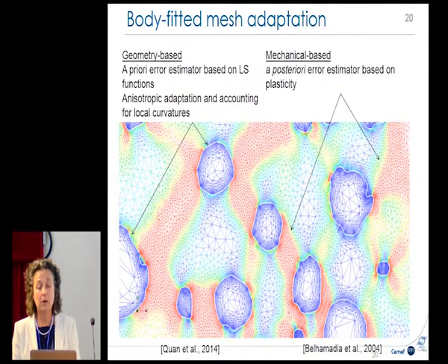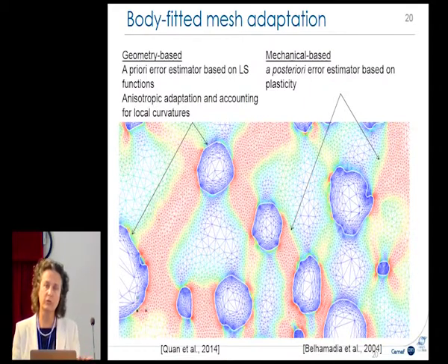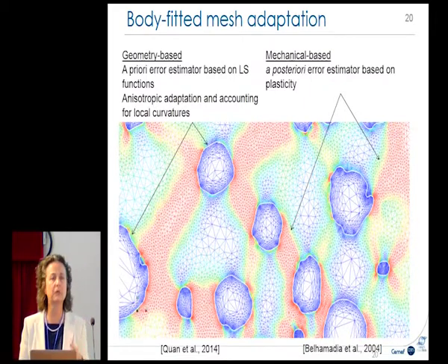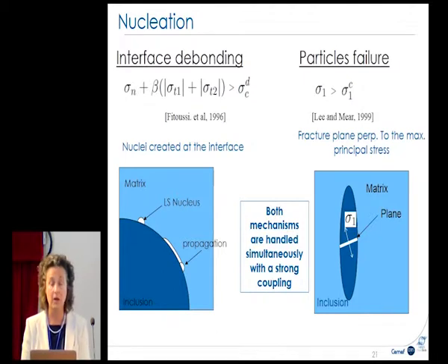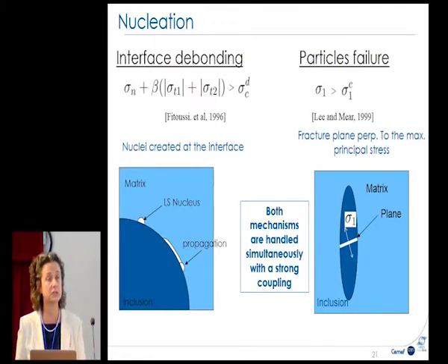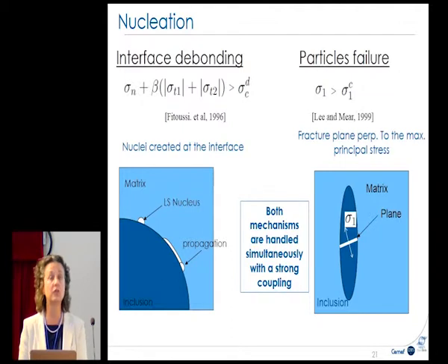In this one, it's very important, as in the previous one, to have the image coming from, for example, the tomography or microscope in order to have the image of the initial defect. We pass a mesh on this, and after we apply thermomechanical conditions on this mesh in order to see the evolution of this damage during the process.